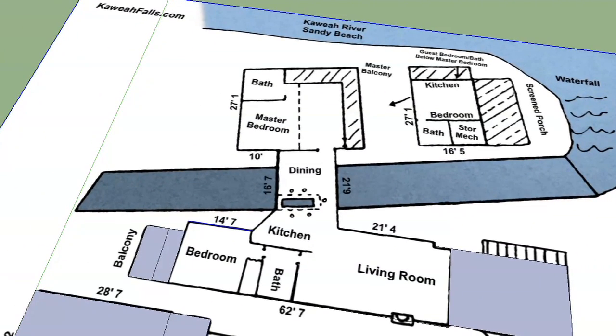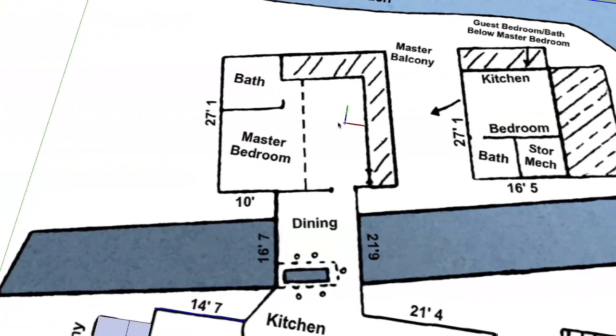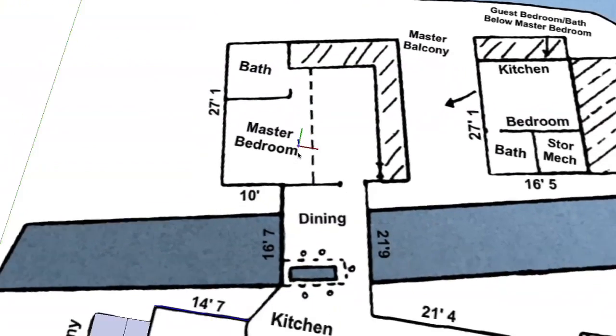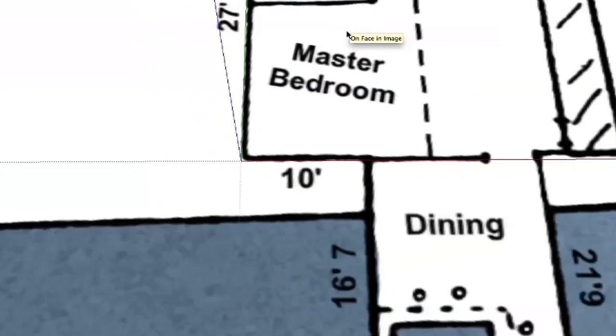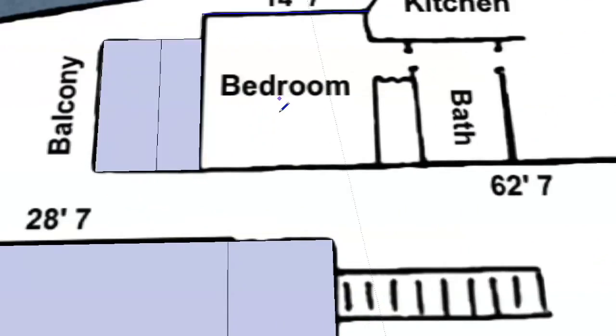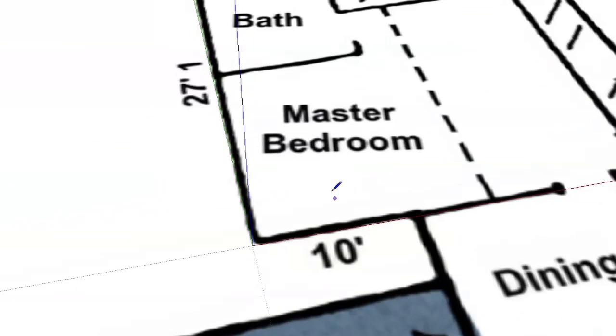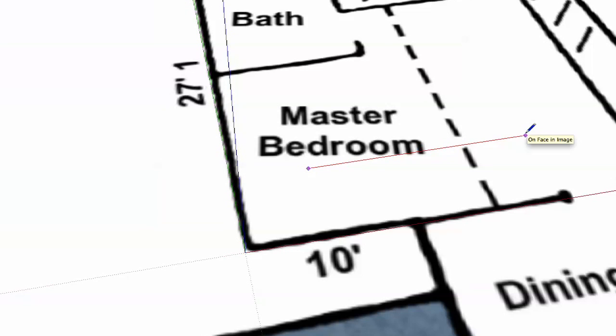So we're going to click on the axis tool, and we're going to go over, and you see this section over here where we're going to be working now is at this kind of strange angle. So we're going to choose this corner down here, and we will click there once, and we're going to set the right angle like that, the red angle, like that. So now you can see if I were to draw a line in the portion of the house that we've been working on like this, you can see that if I lock it in, that is clearly not straight compared to the rest of the house. But if I move over into this section, perfectly straight compared to the rest of that section.